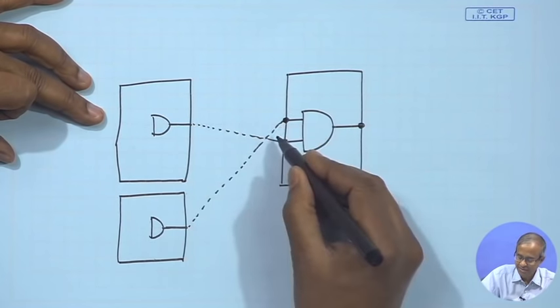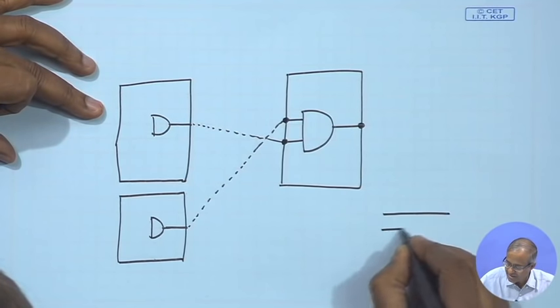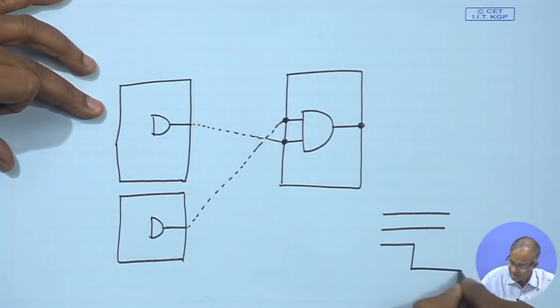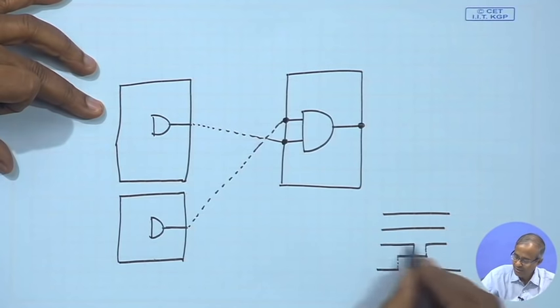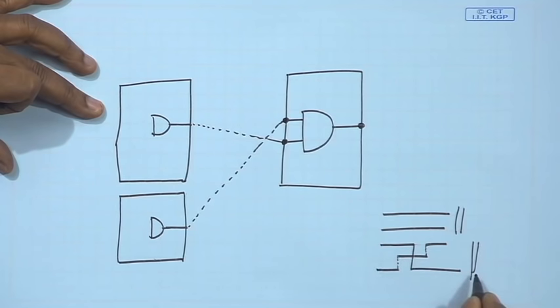Okay. This you can immediately see, because if 2 connections have to be made in parallel, it is easy, but if it is zigzag, then one of them you can connect, but the other one there is a problem. You may have to go to another layer, then again connect like this, then like this. So, you may have to move to another layer, make a connection, and then make the other connection. It will take 3 tracks instead of 2 tracks here. Okay. It will also take more space.